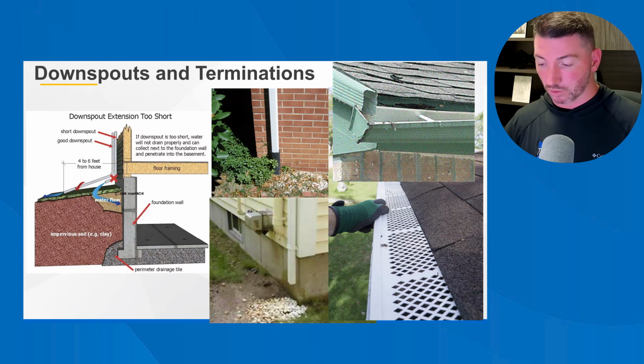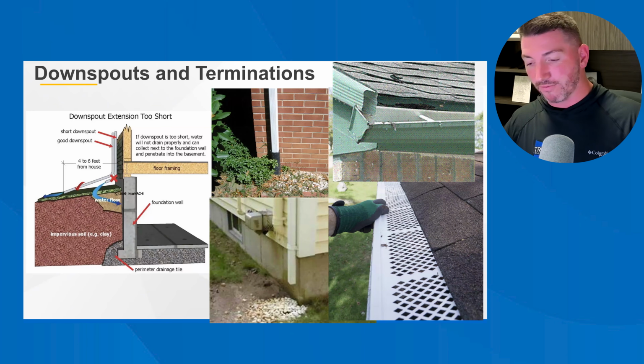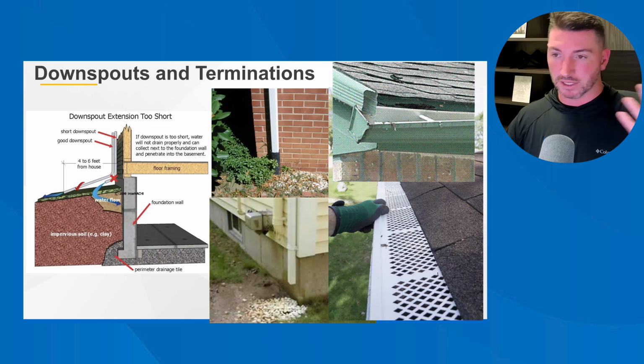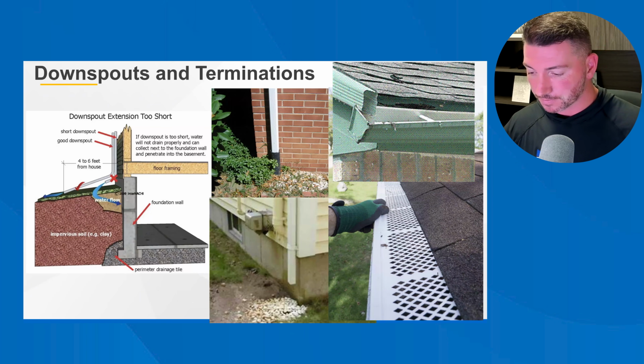So that's just a rough rule of thumb. It's not something you need to put in there and say, building code says this or anything like that. It's a rough rule of thumb just to give you a general idea. Does this roof have enough downspouts to get rid of the water that's coming off of that roof? Or during a heavy rainstorm, is it just kicking over the edge of the gutters?